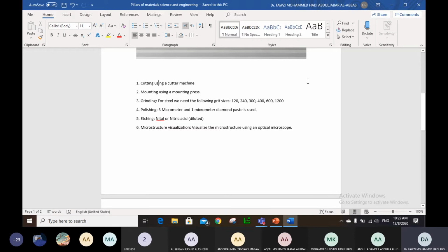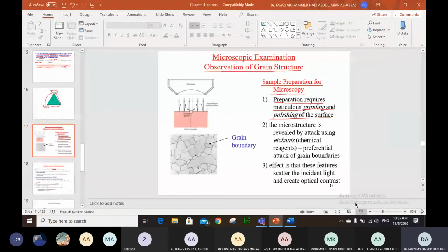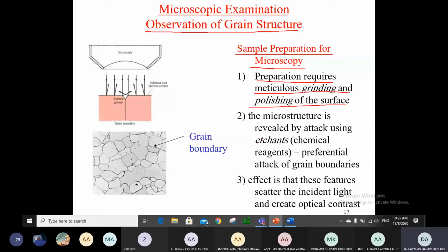let's say it is a tensile test machine. After the tensile test, it is a tensile test specimen. After doing the tensile test, the specimen looks like the tensile test specimen. After breaking, basically, it will look something like that. After, let's say, it is necked and it has formed a cup cone failure, basically. I mean something like this. So you need to sample that. Basically, you need to take a sample of the material and to see what the microstructure is.